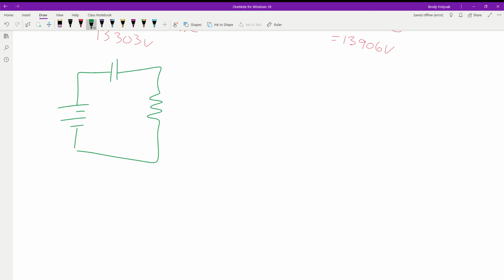When I build these circuits, they're not just to build a circuit, they're with something in mind. Like we had with the loaded bipolar voltage dividers, we're using them to power something else. We have to be aware of where this output is being taken off, because if we take the output here to ground, it's going to give us a different value than if we were to take it off the capacitor.